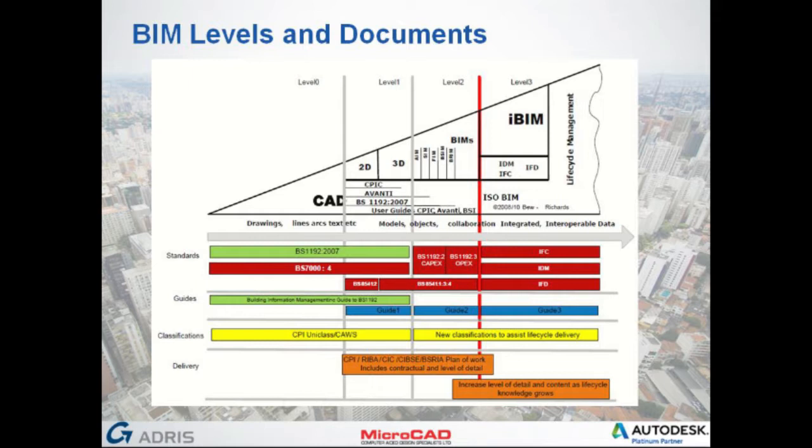So there's a PAS 1192-1, 2 and 3 now, which all handle different areas of collaborative working in a BIM environment. And there are also British standards about modelling creation, family creation, that sort of thing. And then we are now trying to work into things like the Uniclass formats, and things like NBS are now adopting the Uniclass system as well, so that everybody's going to be working in the same sort of way.